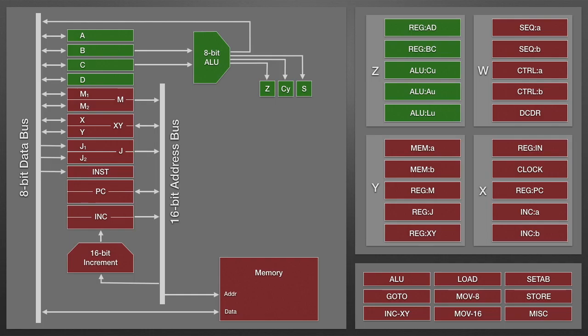This is covered in more detail on my blog, but effectively here it shows that registers A, B, C and D, along with the ALU and 3 condition registers, are all complete. As you can see, there's many registers outstanding, and we're currently without memory or program counter and incrementer.